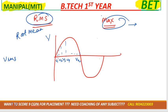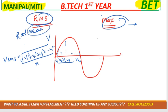VRMS equals root of the mean of V1 square plus V2 square plus V3 square and so on up to Vn square, divided by n. Root mean square means the square root of the average of squares. Okay, and the maximum value is this one, the single maximum value that comes.